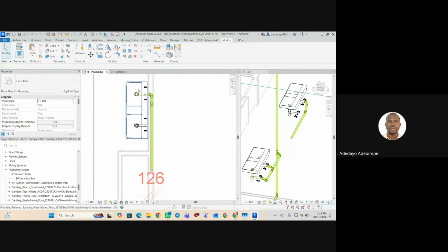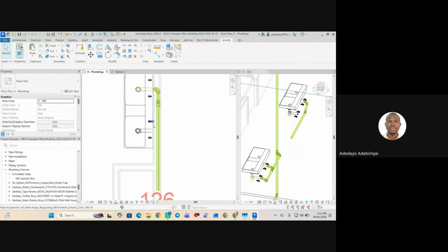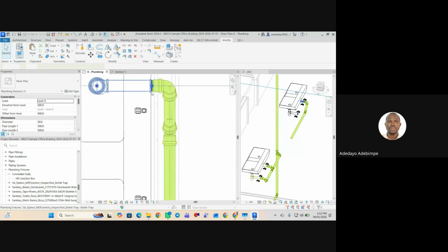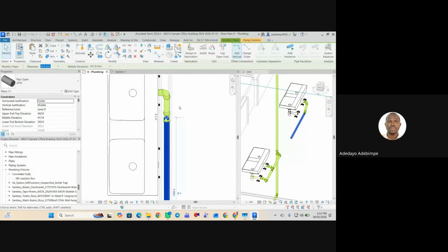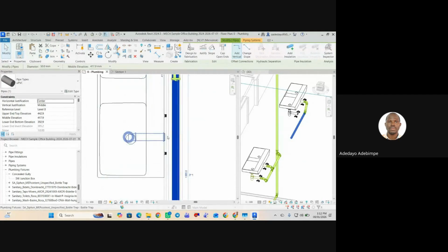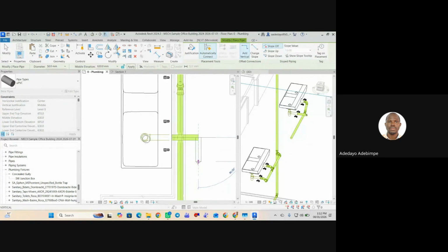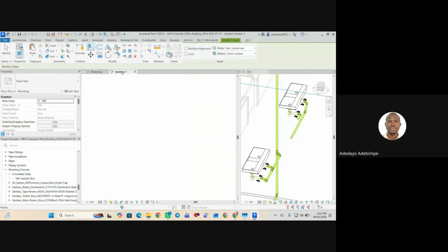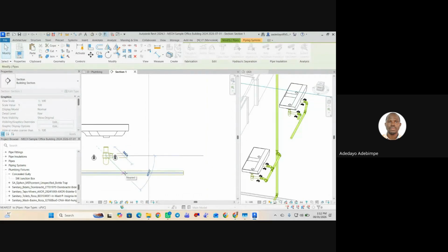Cancel. Now I have a very short room of connection here because this wall is 120 mm. So the trick I'll use is I'll shift my P-trap forward a little to give me a little bit of space. Then I'll do the same, draw out my pipe, a similar, make an elbow. Then I'll do align, go to my section and connect at 45.